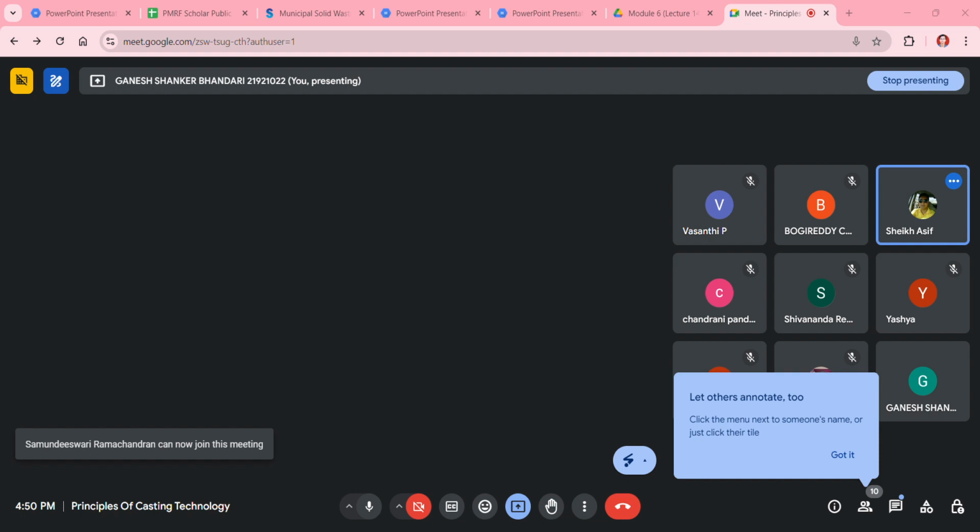We also have some location characteristics. The average distance between container locations is 0.16 kilometer, and the constants for estimating driving time between container locations for both haul and stationary container systems are A equal to 0.060 hour per trip, and B equal to 0.042 hour per kilometer.